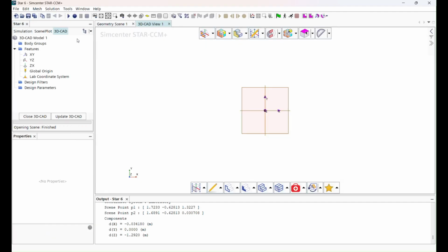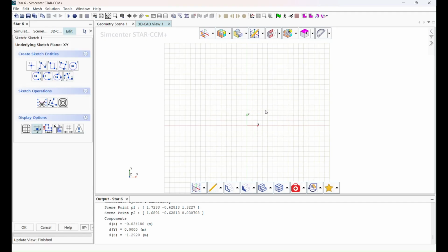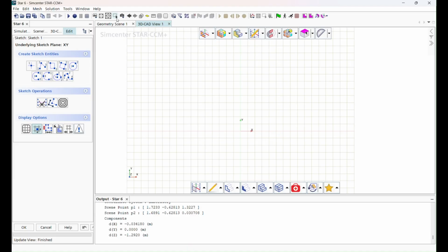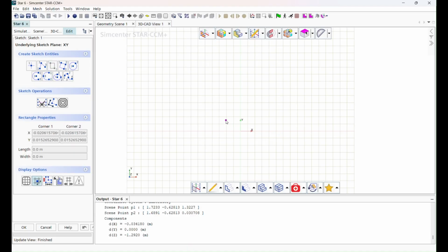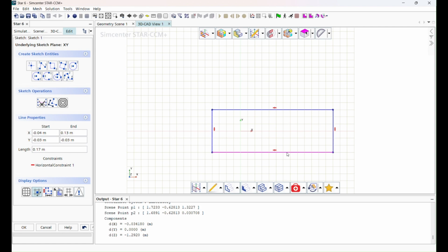Next, we want to create this domain. So create that new 3D CAD model and create that domain and then give it rough measurements. So the rectangular prism is larger than your car's length, width, and height by X amount. Now the amount that you want to make it bigger than your car will depend on you and will depend on your wind tunnel, but I'm essentially giving my car a rough estimation of placing the car closer to the inlet, making sure it is symmetric about the width, and that lengthwise it is a little bit closer to the inlet. Everything else should essentially be symmetric, except for obviously the height. It should not be floating. It should be on the bottom, on the ground essentially.